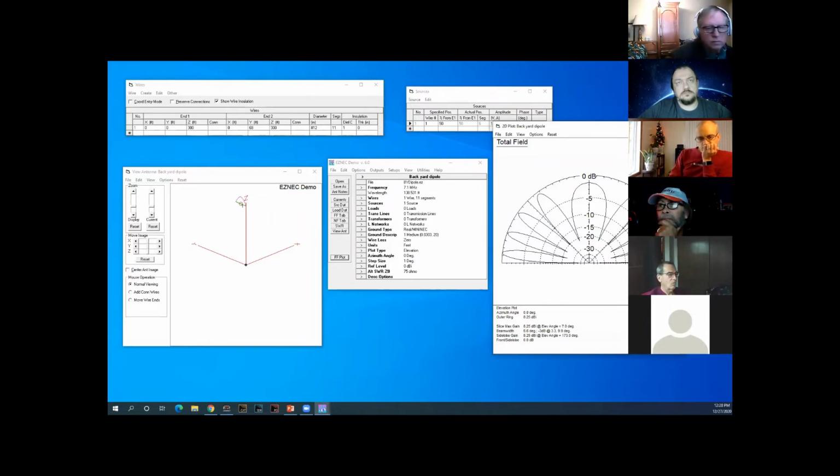So if you look at this, with an antenna up at 300 feet, the big guns, when they have multiple stacked antennas, will very often tell you that their lower antennas hear better than their higher antennas. And this is why: in the elevation patterns, there are these huge nulls as you start getting higher and higher.